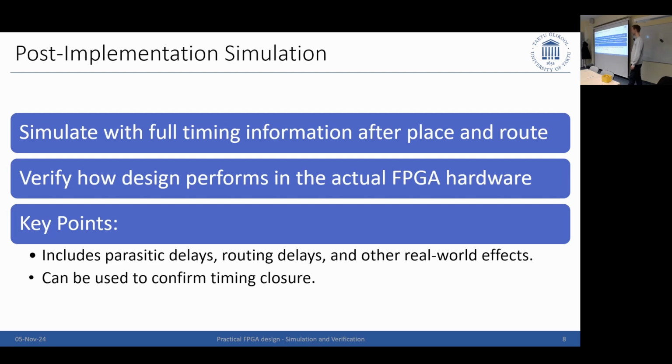I would say the post-implementation one can definitely be 4 times as long, but it's very hard to say. It depends on your tool, and on the license you have, because often the standard license for simulation is limited in performance. Maybe in behavioral simulation I simulate everything, but here I have verified blocks that I do not need to simulate. We will come to how you can spread out your design to make it more efficient. But of course, this will run for a day or longer with a bigger design, and you just let it run through. You do not want to touch this multiple times. It's almost a verification process.